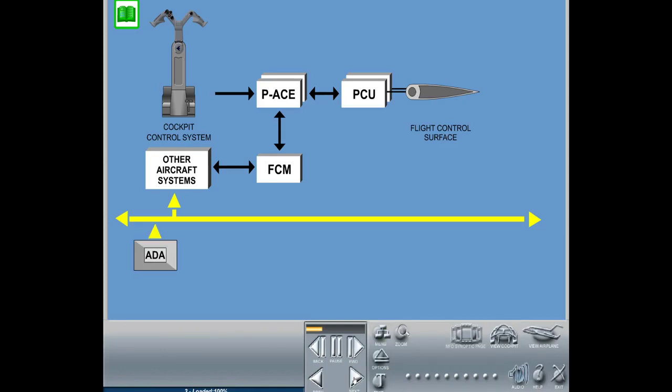Smart probes and the air data application modules provide air data for various airspeed augmentation commands. The inertial reference system provides aircraft attitude and accelerations to the flight control modules used for angle of attack limiting function computation. The proximity sensor evaluation module provides weight on wheels and ground spoiler position data to the flight control modules.